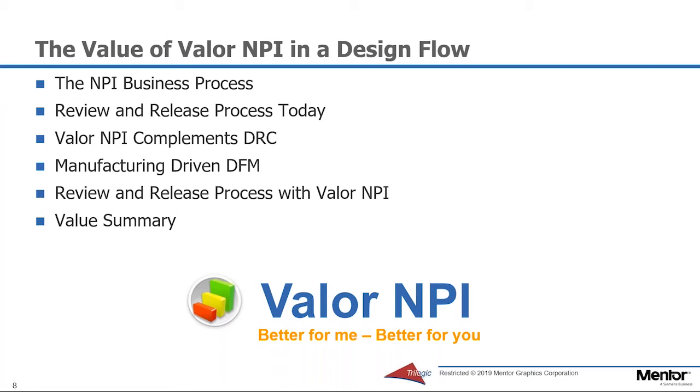We will begin with the NPI business process and review and release process today. We will show how Valor NPI can complement the layout DRC checks and describe what we mean by manufacturing-driven DFM. We will conclude by demonstrating how the review and release process can be improved with Valor NPI. Let's get started.